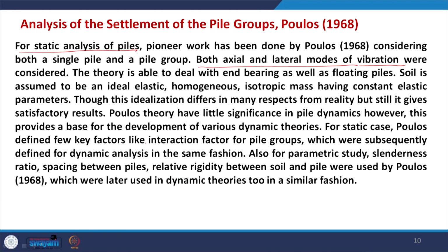So, this term was used later for dynamic analysis also, which were subsequently defined for dynamic analysis in the same fashion. So, Poulos kind of set the trend of using static analysis, then the same theory has been extended for the dynamic analysis. Also for parametric studies, slenderness ratio, spacing between piles, and relative rigidity between soil and pile were used by Poulos, which were later used in the dynamic theories in a similar fashion.